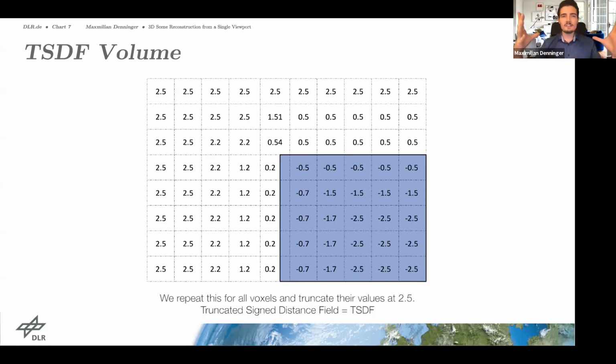So we're always looking just at a camera system. If you have your camera view of your scene, then it already clips right and left, because predicting outside of that is even harder. There are works which try to do that, but it's really, really tricky. And for the depth, if our scene is deeper than 4 meters, we just clip off and we say everything beyond 4 meters is not of interest right now. As I'm working on a robotic system, in this instance, I could just drive there, or get any closer and look up what is there. Okay, so you clip a bounding box to make sure that everything has sort of a homogeneous volume. Yes.